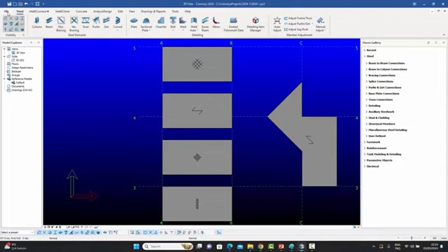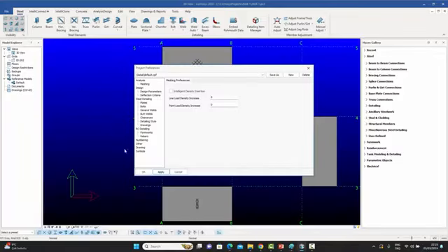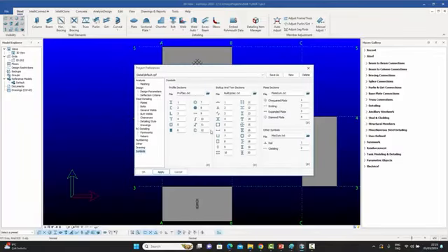I won't be showing that at the moment, but you basically go to project preferences. And if you go to the symbols over here, it shows that for the checkered plate, the grating, the expanded plate and the diamond plates, you can assign 4 different symbols from a particular symbols file. We haven't talked about this, so I don't expect you to understand how the details work.